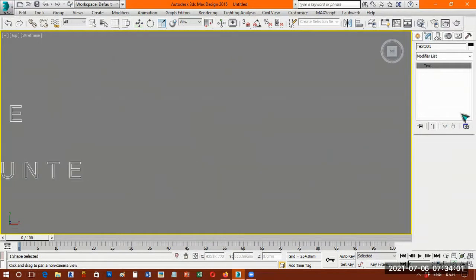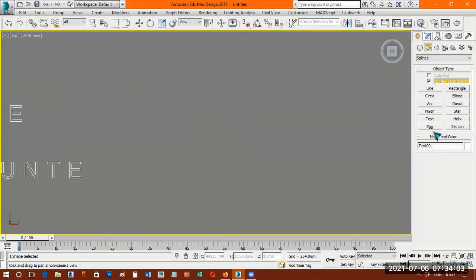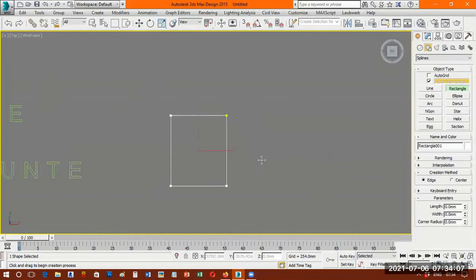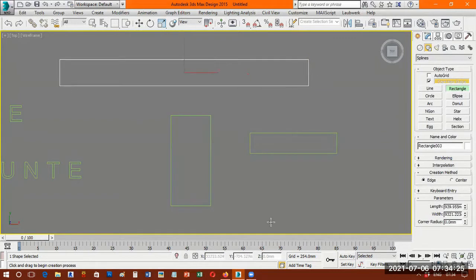The next is, I'll come back to the rectangle topic. Rectangle, click and drag here, that's it. If I hold the Control button while dragging, you'll get a square. All the sides are equal. If I leave it and drag normally, it will be uneven. An uneven rectangle here. I can take it like this. I can generate a beam, column, or wall by using this rectangle.